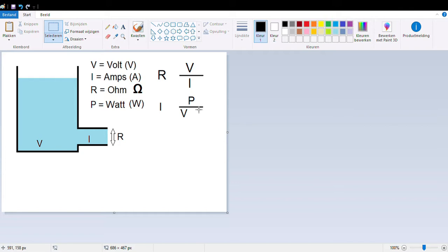Now let's take a look at a 10 volt light bulb, for instance. 50 watts, same kind of energy usage, divided by 10 volts is 5 amps of current. Now 10 volts divided by 5 is 2 ohms. That's quite a bit of difference compared to 800 ohms. So that's basically it. Now let's do some trick. Let's say we connect this 10 volt light bulb to your wall socket, which produces 230. Let's make it 200 volts and see what happens.